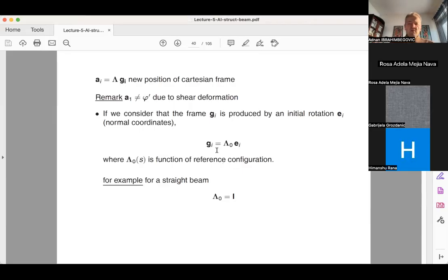In many applications of the beam, people develop this in a local coordinate system, and then they transform it again into the global coordinate system. But if you have a curvilinear beam, it's not so obvious because this local and global coordinate system are changing from point to point. And this is kind of a hassle. So one has to work this out for a really curvilinear beam, as a transition to curvilinear shells, which are always curvilinear. So this was a good exercise.